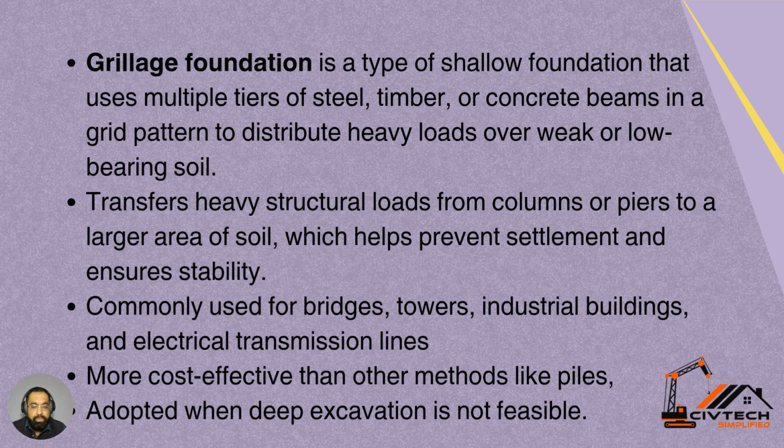Now we will discuss what is grillage foundation and why they are used and where they are used. I will show you the picture of the grillage foundation as well, so that you should have some background knowledge before discussing this question or this topic. So, grillage foundation is basically a type of shallow foundation that uses multiple tiers of steel, timber, or concrete beams in a grid pattern to distribute heavy loads over weak or low bearing capacity.